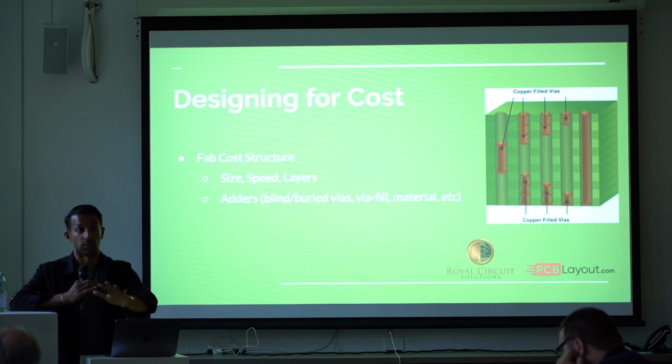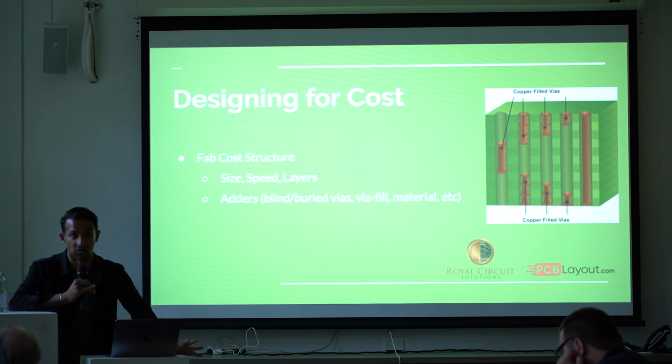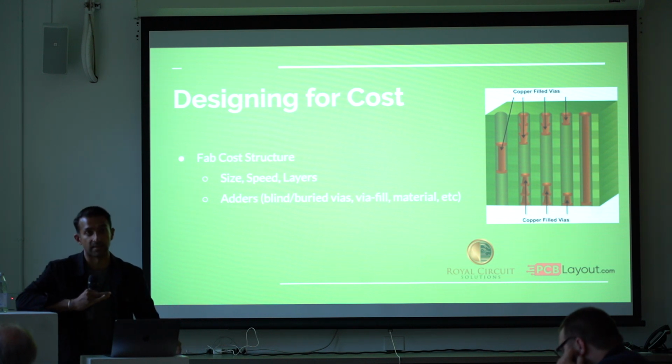The second you get into through-hole or manual assembly, the price jacks up way fast. And that's any assembly shop. So ideally, limit your through-hole parts. That's probably the biggest driver of cost there. And then the number of unique line items, because that's loading the pick and place and things like that.